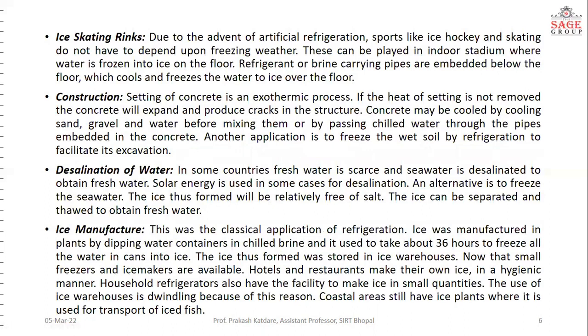Ice skating. Due to advent of artificial refrigeration, sports like ice hockey and skating do not have to depend upon freezing weather. These can be played in indoor stadium where water is frozen into ice on the floor. The refrigerant or brine carrying pipes are embedded below the floor, which cools and freezes the water to ice over the floor.